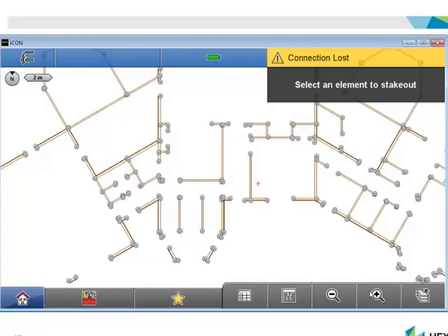Incidentally, to check the code of a line rather than a point, because I selected a point there, you'd need to begin measurements before this information is displayed. So the best way to get this layer information before connecting to a GPS or a total station is to turn show points to on and select a point that will be part of that particular layer, and then use the code reference in the info panel to identify that code. So that's the US House DXF, and I'm sure you can agree that it's a lot more manageable now.